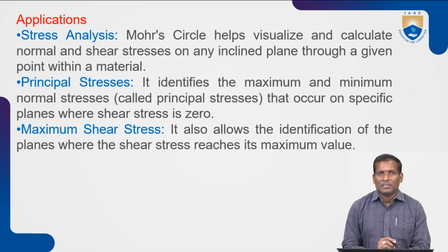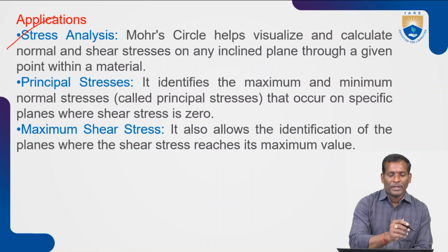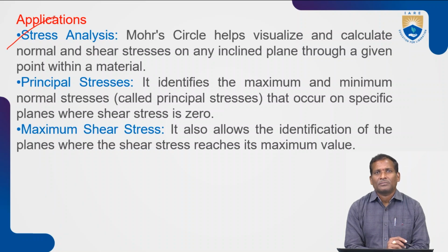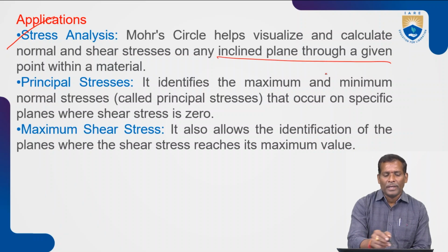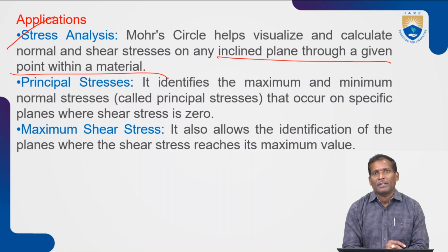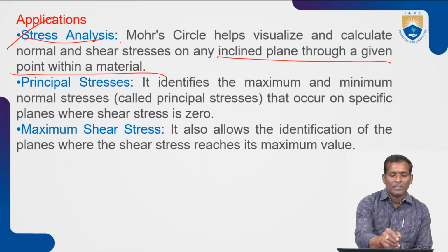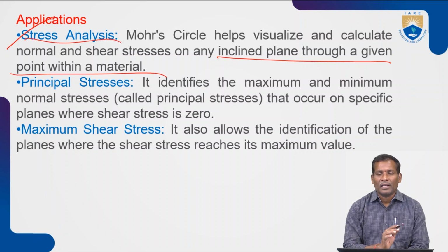So what are the applications of this Mohr circle? One is stress analysis. Mohr circle helps visualize and calculate normal and shear stresses on any inclined plane through a given point within a material. In stress analysis, we calculate the normal and shear stresses on any inclined plane.